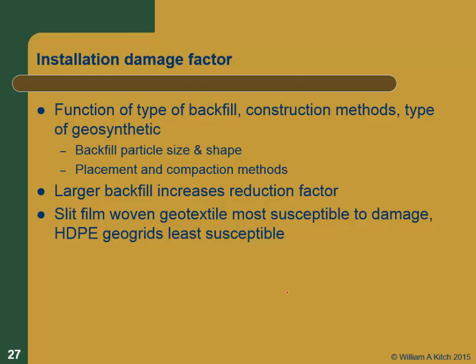The slit films, I didn't discuss it. There was a slit film here. If you want to come up and look at this afterwards, some of the slit film, those plastic tarps that you use for everything, the blue ones and the green ones, they're all slit film. Look at one of those sometimes. If you look at them, you'll see that they're actually woven out of very thin, wide elements, relatively speaking. They're called slit film because they take a film like a garbage bag film, and they slit it, and then they weave it. They're the most susceptible to damage.